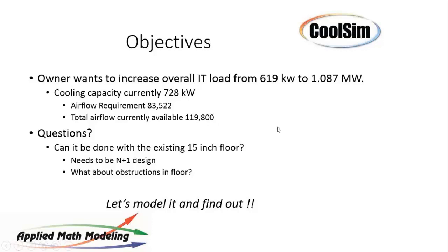The webinar is really on where we're going to go, and this particular customer wants to take this data center up over 1 megawatt. And the questions become, can you do it with a 15-inch floor, with N+1? They want it to be N+1. What about the obstructions in the floor? Modeling is a great way to find out. There's a few things you can do right offhand. The total airflow currently available is only 119,000, so we're not going to be able to get up there with our current system. We're going to have to either retrofit what we have, add capacity, or something.